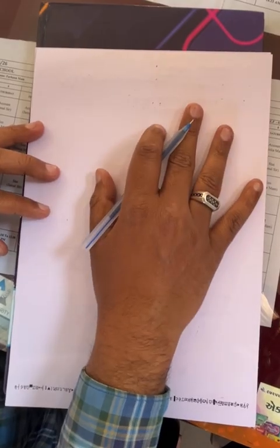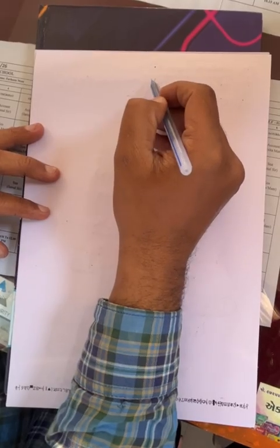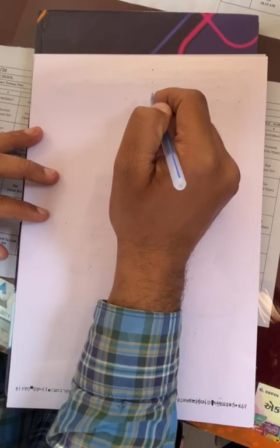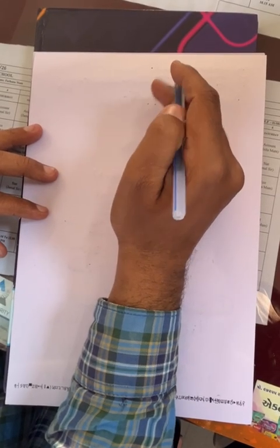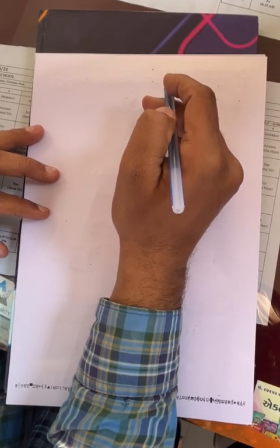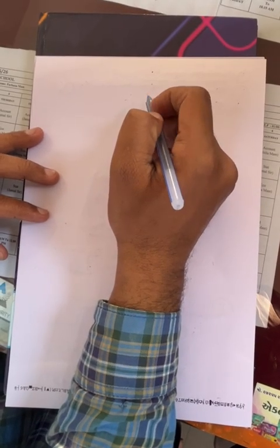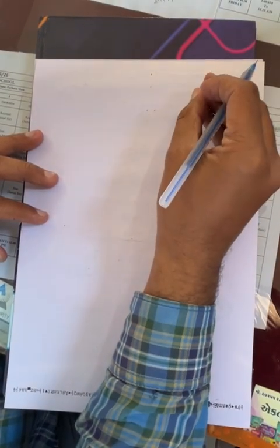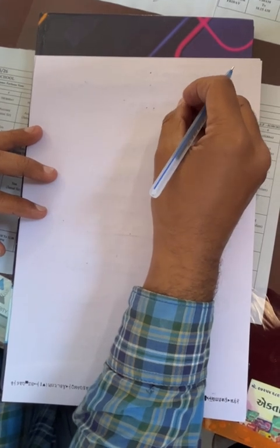So in this video, in a previous video, we checked the radius. We have a heavy zone, hilly area. We have a super elevation. We have a friction, and we found out the difficulties by checking all the different conditions, and we decided on our radius of 250 meter. We reduce the design speed.